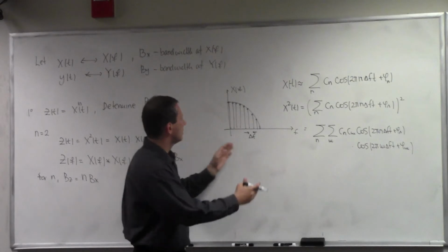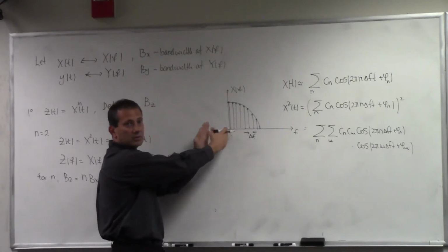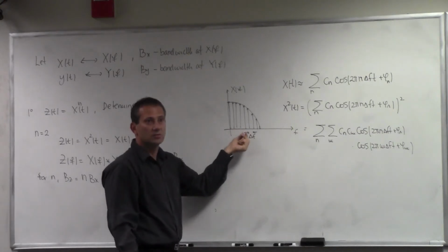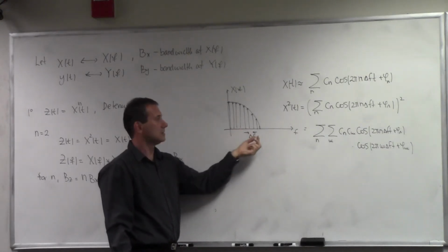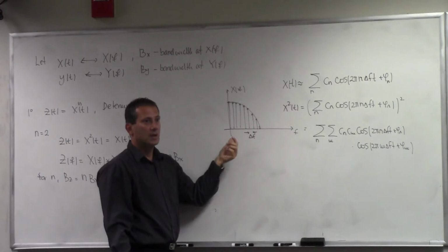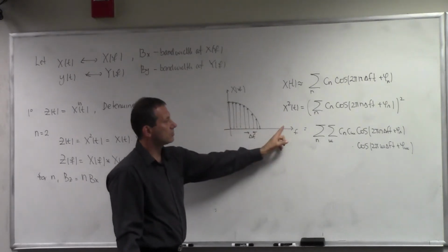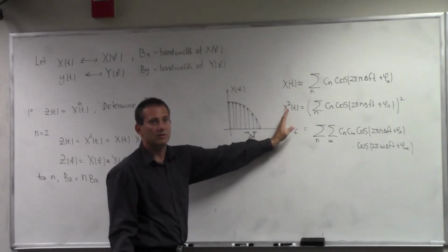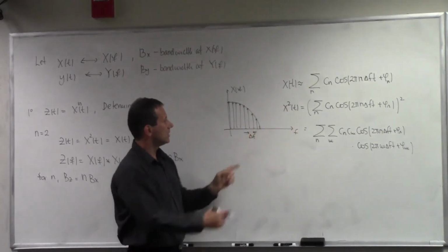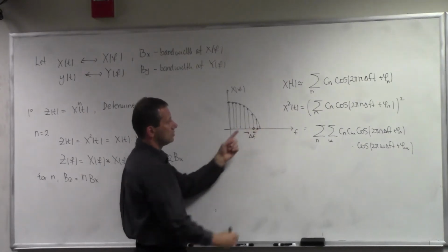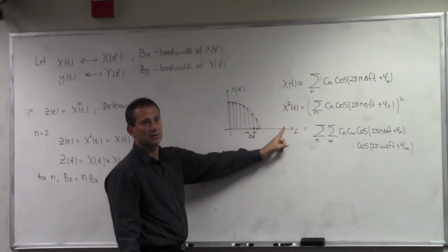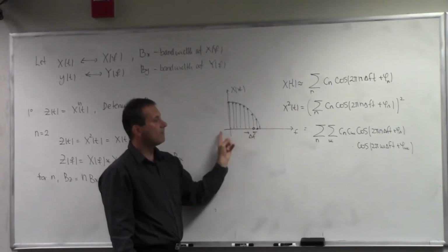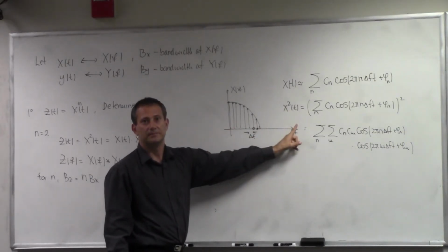The differences are going to generate components that are towards the origin, because the difference can be as small as 1 delta f. But what will push the spectrum of the signal out are the sums. Sums are going to extend beyond, because look at, for example, the multiplication of these two. Their sum is going to be here. You follow so far? So how far can the sum extend?